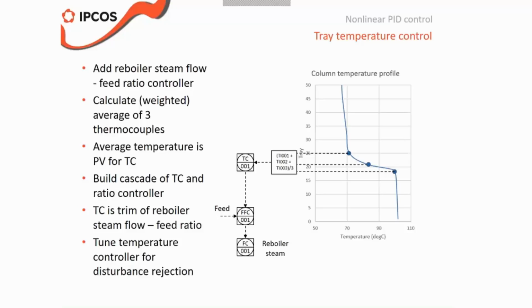Let me read the question again for Arthur. The question is, suppose you have a buffer in the pH control which shifts from run to run, and therefore the response depends on the flow. Is the characterization block still the right solution, or is there something else you could do?